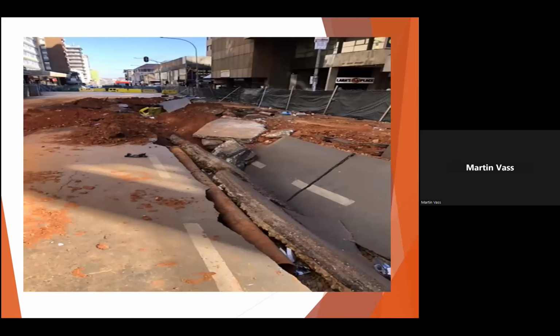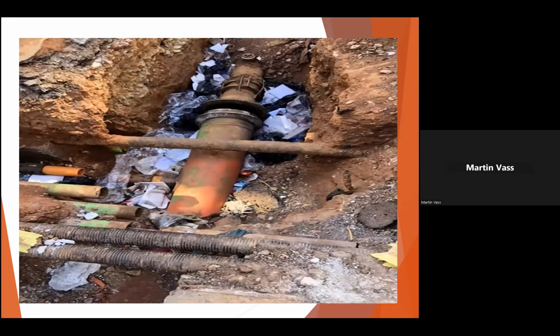I understand from the latest press releases that the council has allocated a certain amount of money to rebuild Bree Street, which is a major taxi route. My own feeling is I think you should just turn it into a pedestrian walkway. And I say that because look at the amount of services in the ground. Each of these services has to be tested to see if they're live. If they are live, you then have to establish from where and to where they're going. You then have to reroute that service and then move on to the next service. I think it's just easier to turn this into a pedestrian way, but that's not my decision.